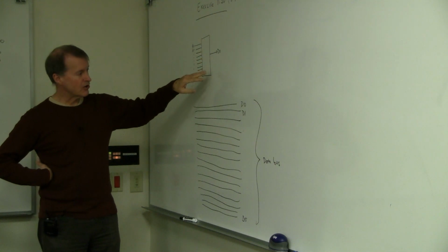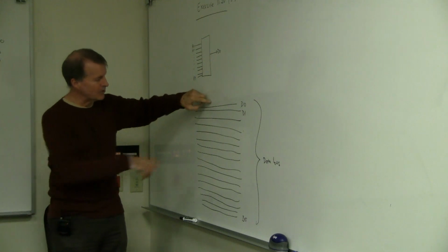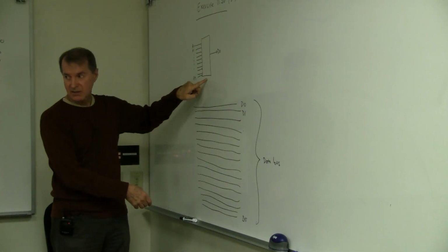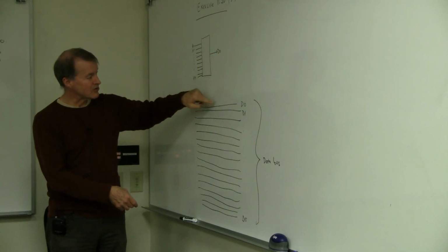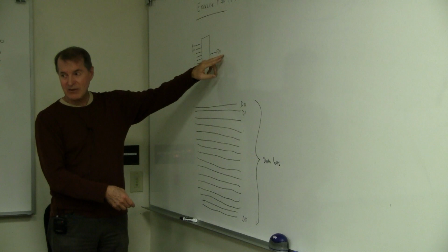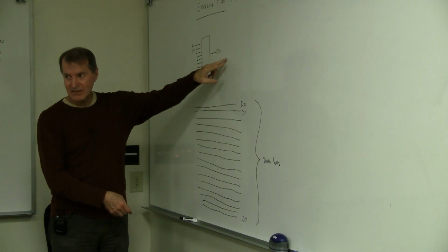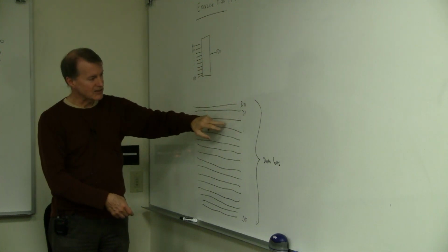But how many are you going to hook up? How would you hook these devices up to fully populate the data bus? How many of these chips would it take? 16. The D0 of one would go to the D0 of the bus. The D0 of the second one would go to the D1, and the D0 of the third would go to the D2.